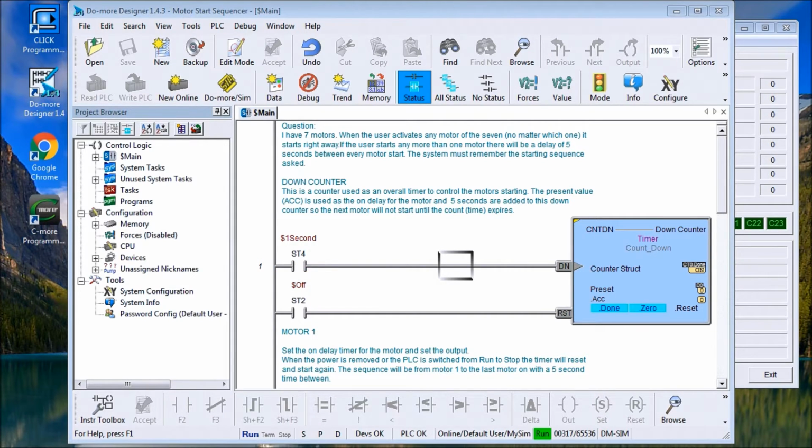So if you can picture, for example, all 7 switches and someone comes up and turns them all on at once, you want to avoid that inrush of current to start those motors. And in order to do so, what we have to do is come up with a program that'll do that.